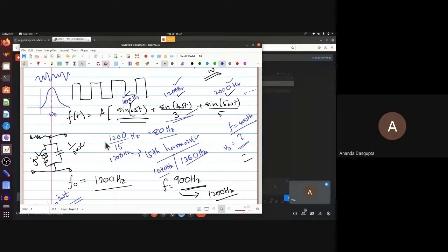The question is, we usually call this experiment, when it's done in the lab, determination of the Fourier spectrum. But the Fourier series looks like this, right? For a square wave, you give it a particular omega, it has omega, 3 omega, 5 omega, etc. So the natural thing, if you wanted to determine a Fourier spectrum, I expect, would be give a particular square wave, use a resonance circuit with different resonance frequencies, and change that resonance frequency and cross check. Okay, you get my point?